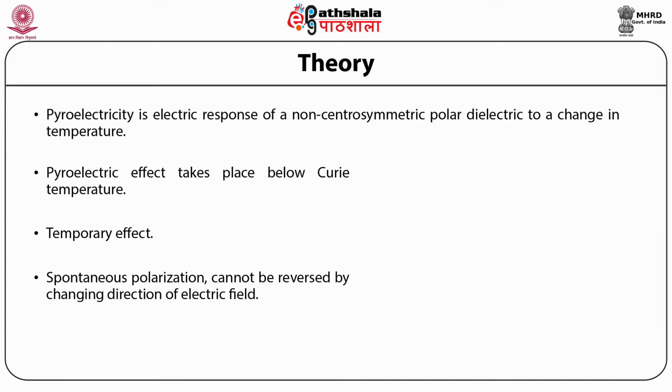Pyroelectric effect takes place below the Curie temperature. When the material is heated above the Curie temperature, the atoms come back to their equilibrium positions. The electrocaloric effect is considered to be the physical inverse of the pyroelectric effect. This pyroelectricity should not be confused with thermoelectricity. In the case of pyroelectricity, the whole crystal is changed from one temperature to another, resulting in a temporary voltage across the crystal. Whereas in the case of thermoelectricity, the two ends of the device are subjected to two different temperatures, resulting in a permanent voltage across the device as long as there is a temperature difference.